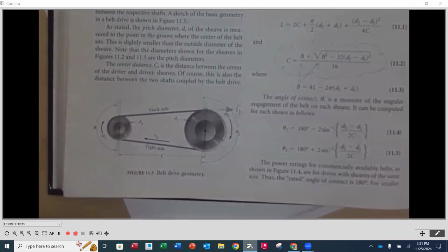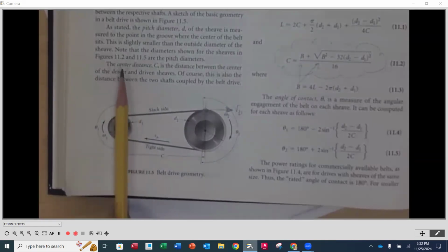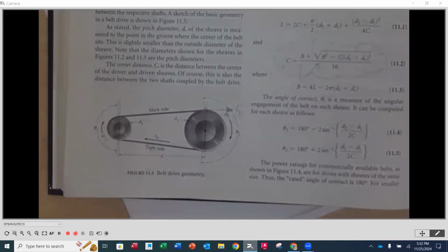Now it's not part of this class in kinematics, but when you do machine design elements, you are going to be picking belts and sheaves out of a catalog for an actual vendor. And then you're going to be specifying not only what we call the take up, but also where you have to push it in so that you have enough to get the belt over the top. Those are design elements that you have to build in.